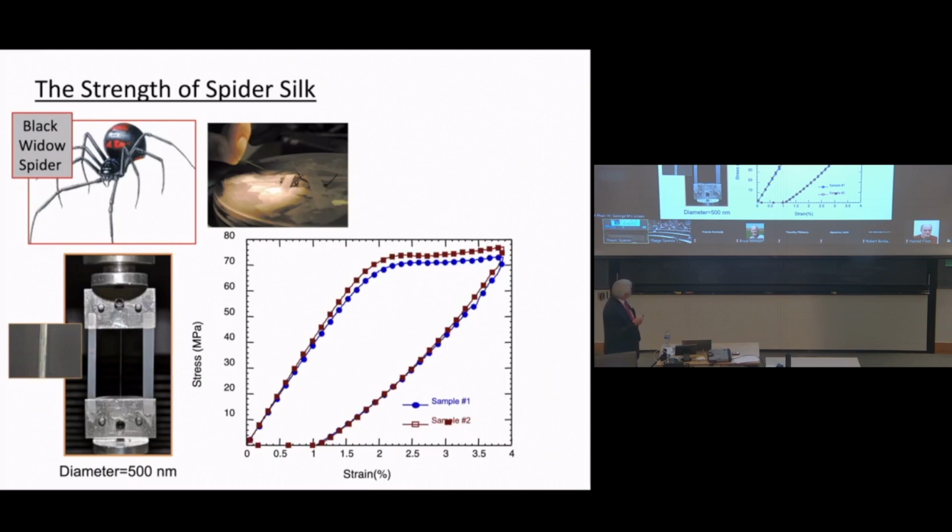If you tape these things down and stick a pin into this thing called the spinneret, you can actually pull a single fiber out of this thing. And you can do a test. You can do a tensile test on that single fiber. And these fibers have diameters that are, well, this one in particular is about 500 nanometers. So you really couldn't see this thing with your naked eye. You can see it here because the light's reflecting off of it in sort of a funny way.